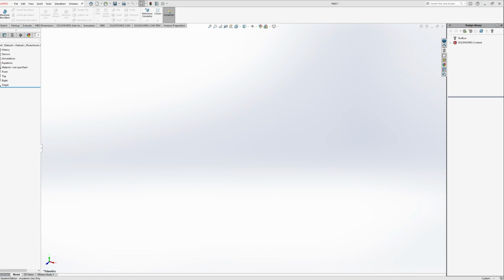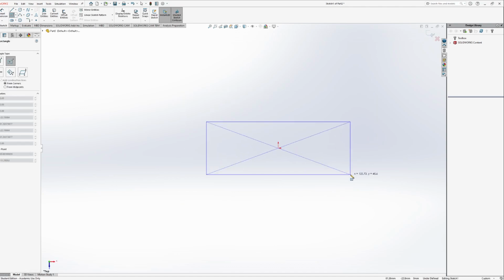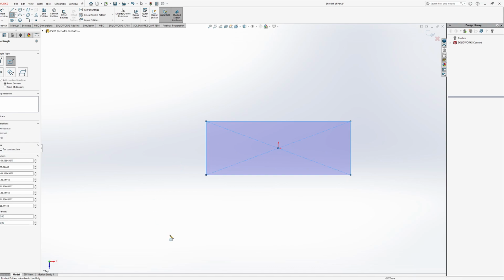But mostly what we are going to do now is start creating our part, making sure that we're integrating the variables that have been assigned. So I'll create a sketch and I'll create a center rectangle on the top plane. So I have this here, and our diagram tells us that the dimensions of the base are going to be 5a and 2a. So one measurement is basically going to be a 40 by 100 rectangle here.